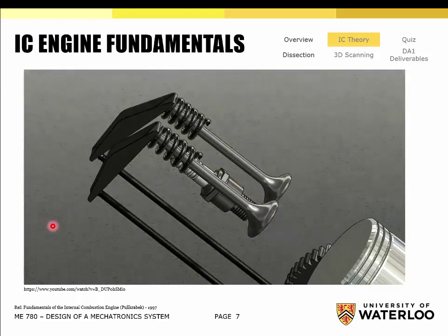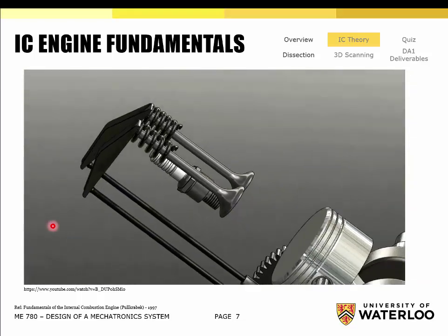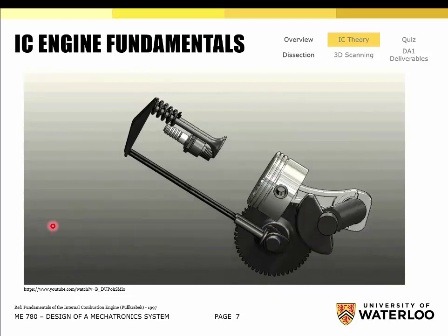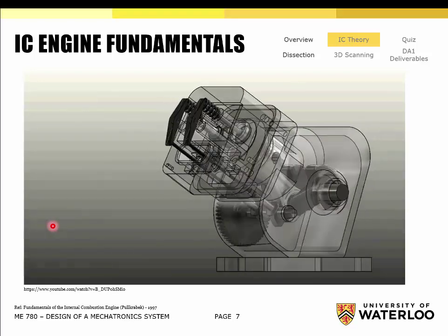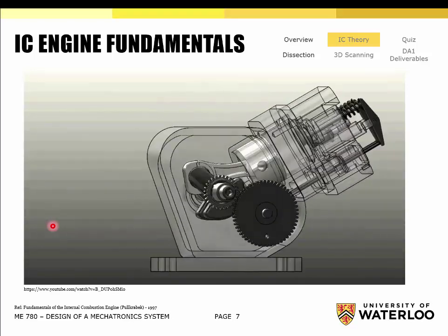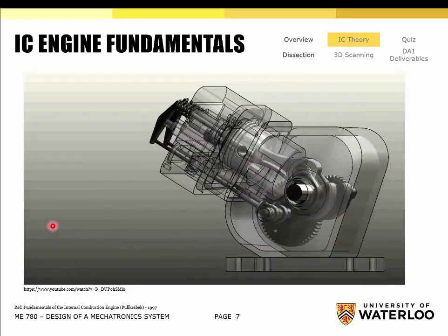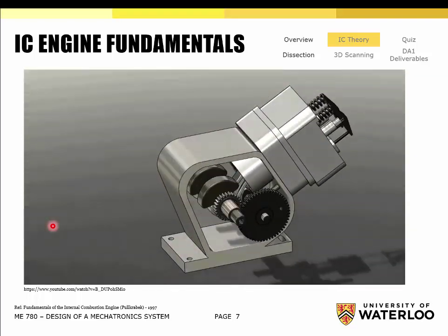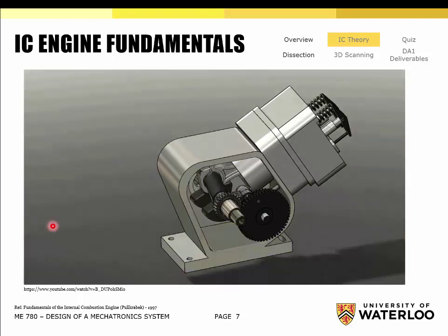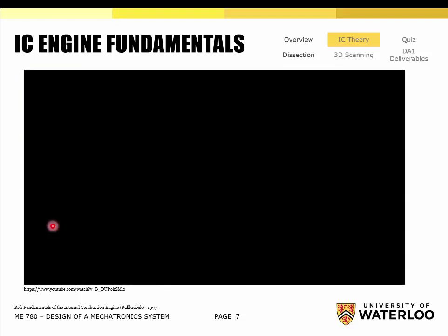Change the speed, okay, of course, yeah, it's definitely changing the speed. So is it making the speed higher or lower? Lower speed. Okay, great, that's the right answer. Why do you think it needs the lower speed? What is that gear hooked up to? Yes. We don't want the camshaft, the valves, to open at the same speed as the crankshaft. So you said the camshaft operates at the same speed or a lower speed? Lower speed. Okay, yes, that's very correct.